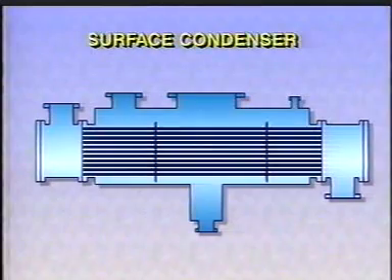The heat exchangers we've seen up to now have all been used to heat a process liquid. In some instances, however, the purpose of heat exchange is to remove heat from a fluid that requires cooling. Suppose we wanted to convert steam generated by one process into feed water for another process. To do this, a shell and tube exchanger can be used as a condenser. This cutaway will show how the condenser works.